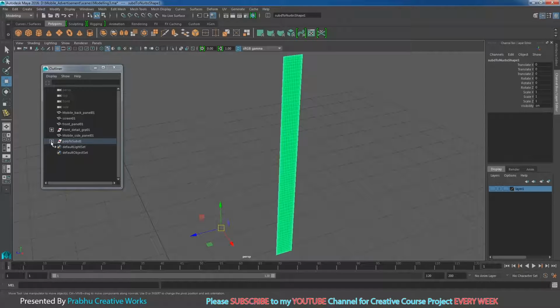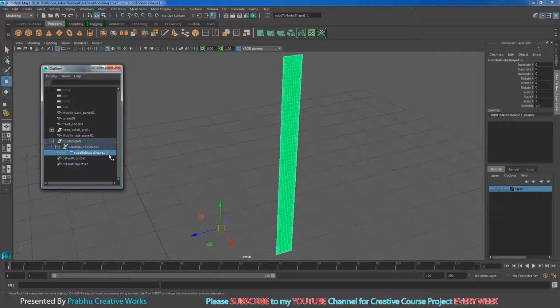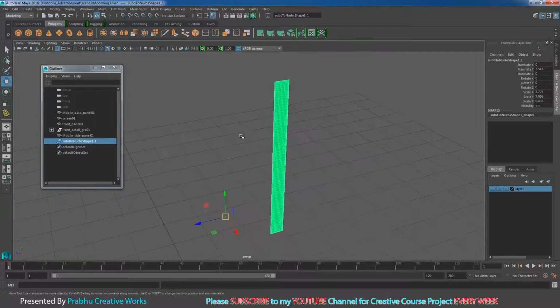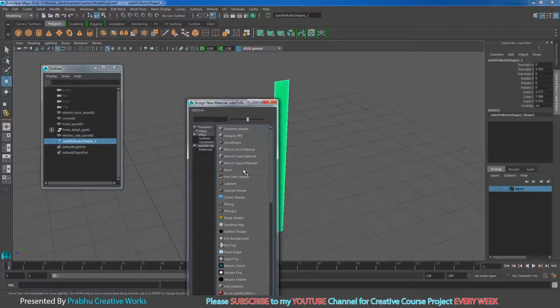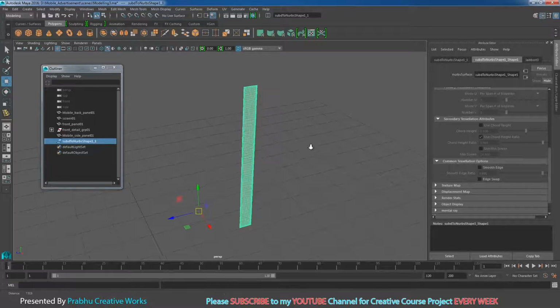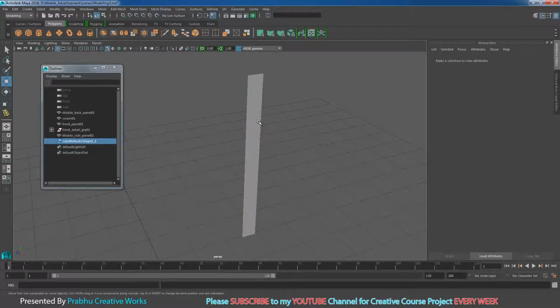Expand this group, expand this one and click on this one, press Shift P on the keyboard, so that means it will leave the group. Select this object, go to edit, delete by type and choose history. I will select the poly to sub-D group and press delete on the keyboard. Now we have only the NURBS shape. Now right click over here, choose assign new material and choose Lambert. So now our object should be clean.